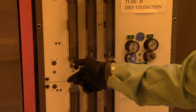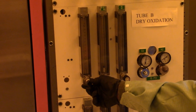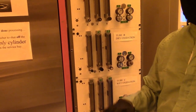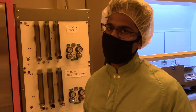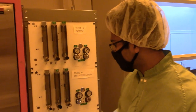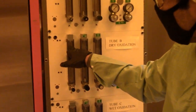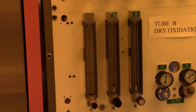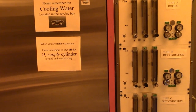Based on the flow rate, set by a mass flow controller over here, you can change the amount of oxygen entering the furnace, and as a consequence have a certain level of control over the growth rate of the oxide. For this process, we'll be using a flow rate of around 150 here, which correlates to around 1.5 liters per minute. And let's go on and load the wafer into the furnace.